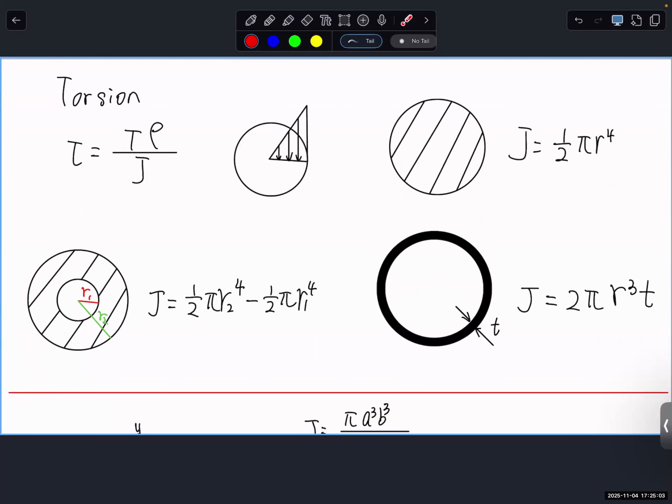No, it's a different thing. So let's say tension compression. I apply force upward, reaction force downward. This is tension or compression, right? If I bend in this way, this is the bending moment. Torque is, let's say I still clamp here, but I apply a torque in this direction about the axial direction. It's a rotation moment about the axial direction.